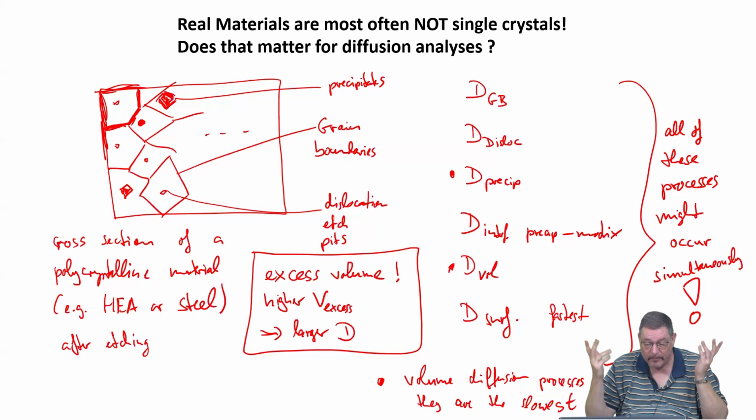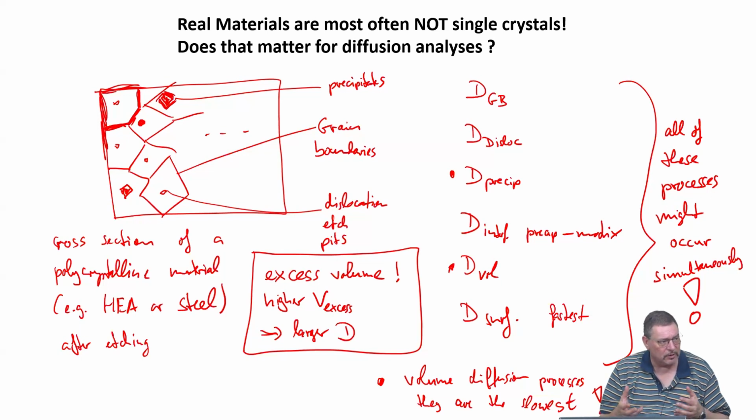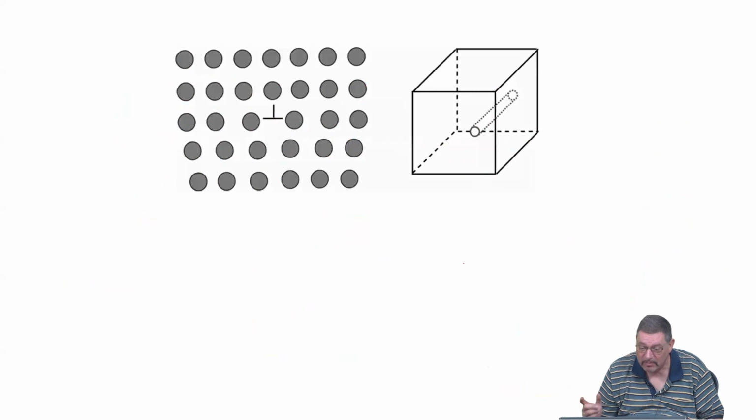And this is a very nice mental picture, and actually one can show by computer simulations, there was just a paper last year, that this can actually be done in a quantitative way. So you can derive a model, computer model for diffusion in grain boundaries, which is just parameterized by the excess volume present in a specific grain boundary. So it's a mental picture that is really rather accurate, which many mental pictures are not.